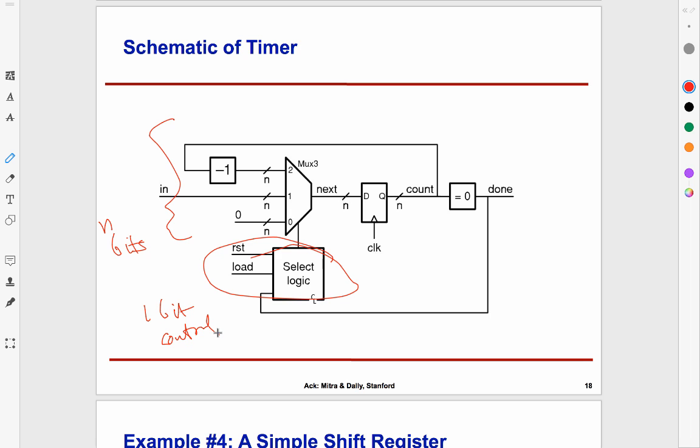So there are versions of Verilog which are meant for this kind of high-level thing. So there's something called SystemVerilog. But a very common thing is to actually just use C. So you write your hardware description in C. It goes under the name of SystemC. And then, instead of running it on a regular compiler, you run it on a different tool, and it kind of figures out all these things.